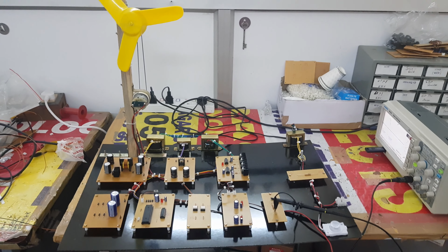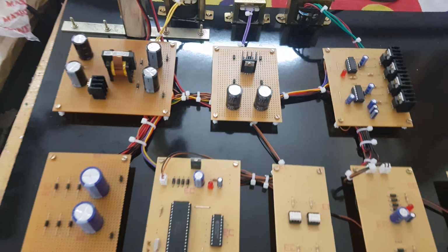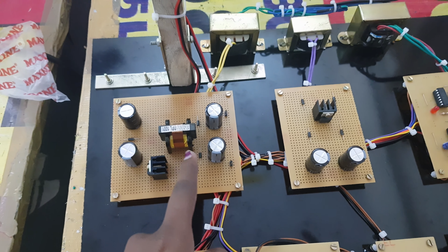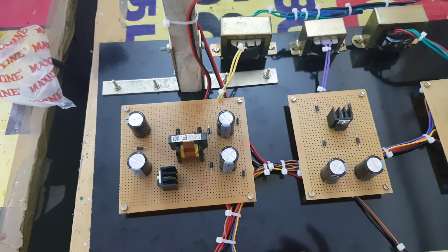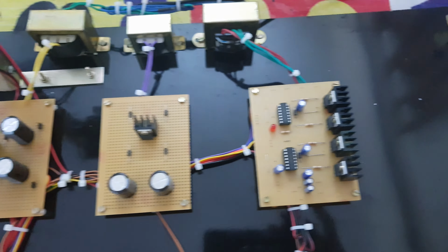So the title of this project is Novel Isolated Power Conditioning Unit for Micro Wind Turbine Application. For the turbine over here, we used a model prototype of a wind turbine, and this is our converter. This is the coupled inductor over here. This is the quasi-Z-source with the coupled inductor arrangement, and this is our inverter,